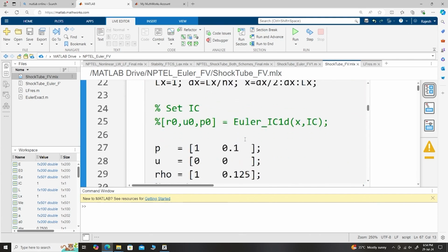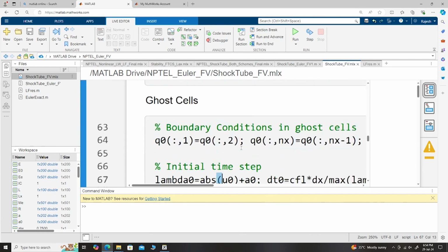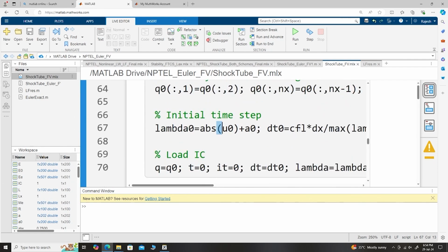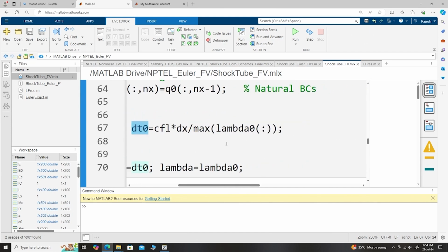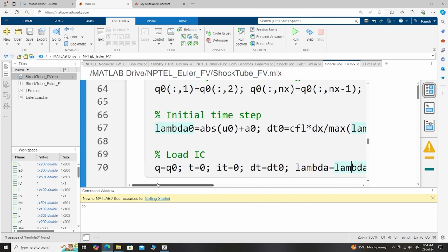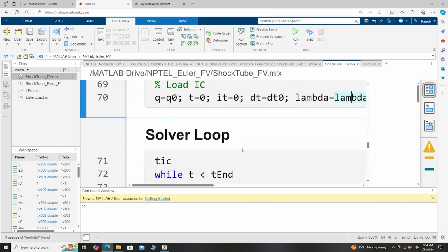So, you can take the value of 0.5 here, and calculate your delta t based on the CFL condition, so C delta t by del x equal to 0.5. This is the initial, and as your values of u and a change, you can update the value of dt.